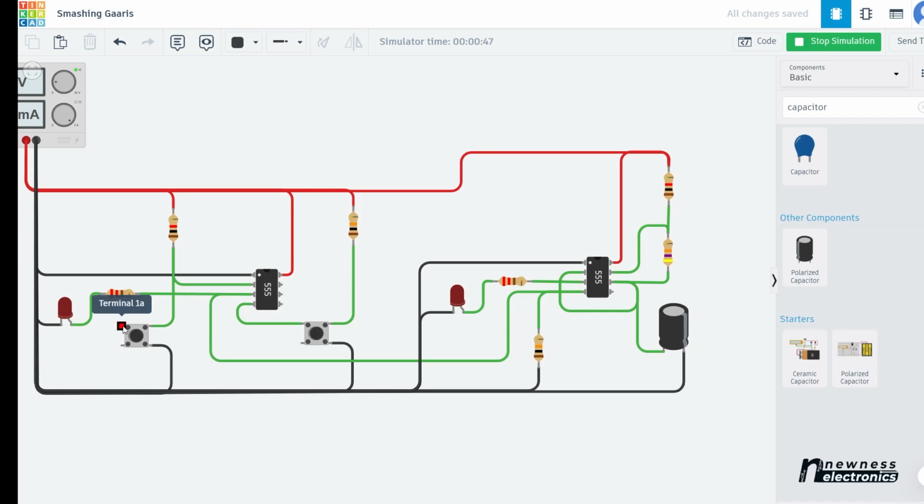You may think, why do we need this kind of button when you can just put a heavy button on the power supply? Have you seen an inverter before? Do you realize that most inverters are controlled by just that small button switch? That means they are not switching the power to the inverter from the power line. They are using signals like this to control it. So when we are building an inverter, we can use something like this too, such that this thing will not oscillate except when I press the power button. That's when it will start oscillating.